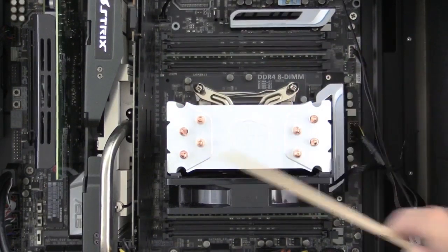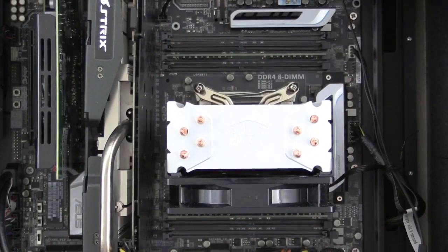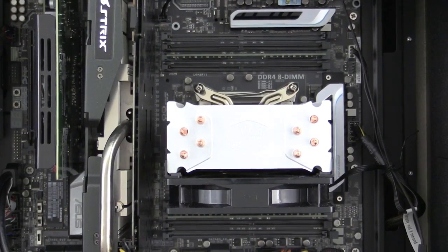You might have noticed it did have some movement, even though there's some standoffs on the motherboard between the motherboard and the case. There is always a little bit of movement. Never force it though. If it feels like it's not going, try not to force it. Okay, so that is the RAM install. The physical install really doesn't take very long.